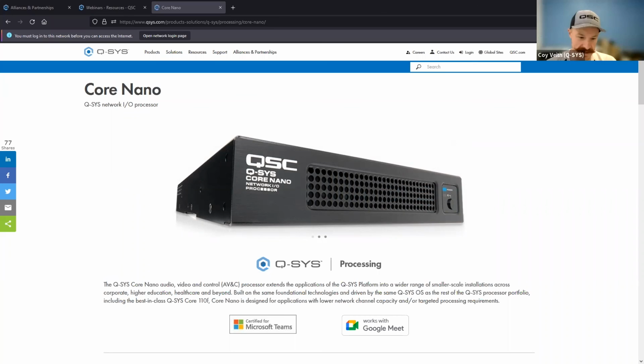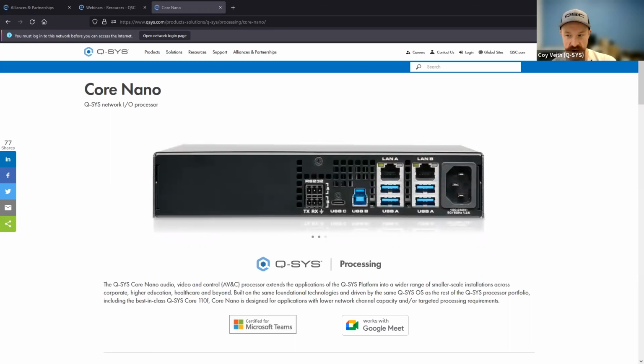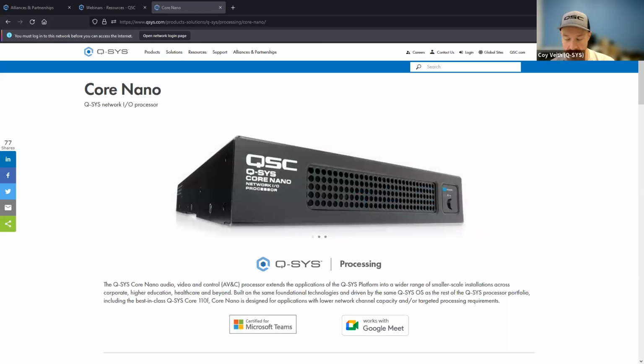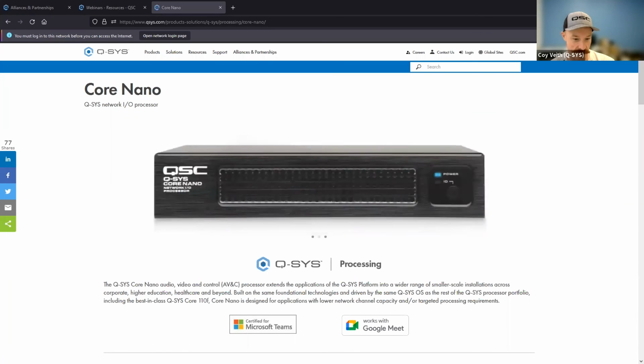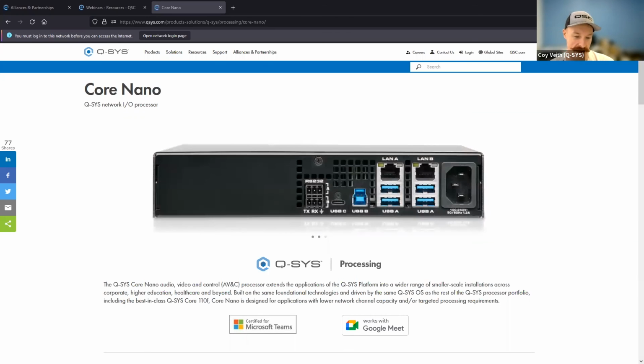To offer up an idea, I'm not saying this will work, I absolutely say test this, but if you wanted that single cable for an end user, you could potentially look at using some sort of a PC dock, and then take the outputs of that, one being USB to the core, the other being your HDMI to whatever extender you're using, or NV32, whatever it is. And then you could offer up that single cable, but I would test that.